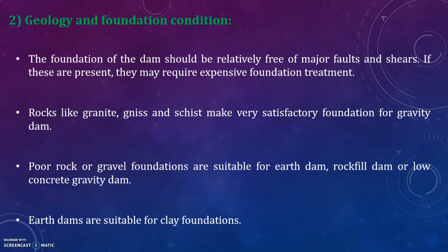Poor rock or gravel foundations are suitable for earth dam, rockfill dam, or low concrete gravity dam. Since there will be considerable underseepage in this case, effective water cutoffs or seals have to be provided. Silt or fine sand foundations have the problems of settlement, seepage, and toe erosion.